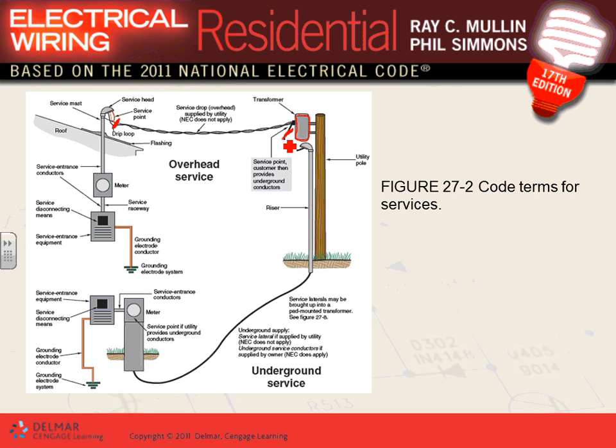Derek, my friend, from this point here through the pipe all the way down, this is designed and built by the electrical contractor and electrical engineers, and owned and operated by the owner of this building. Versus this cable here, which is owned and operated by the electrical utilities. This is called your service drop. Can I get you guys to understand that who owns what is so important? My service point is right here.